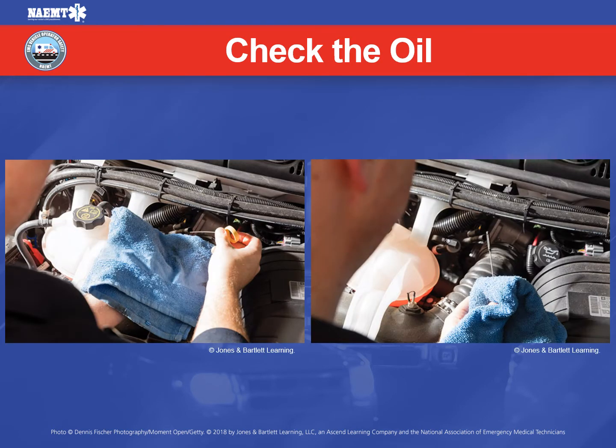Perform an oil check and adjust levels as needed. Always follow your standard operating procedures and document the vehicle check and any adjustments made or any fluids that are added. In addition to looking at the oil level, check the color of the oil, and smell it to see if it's burnt. See if there's any liquid or milky substance or water in the oil as well. All of these indicate a mechanical failure.